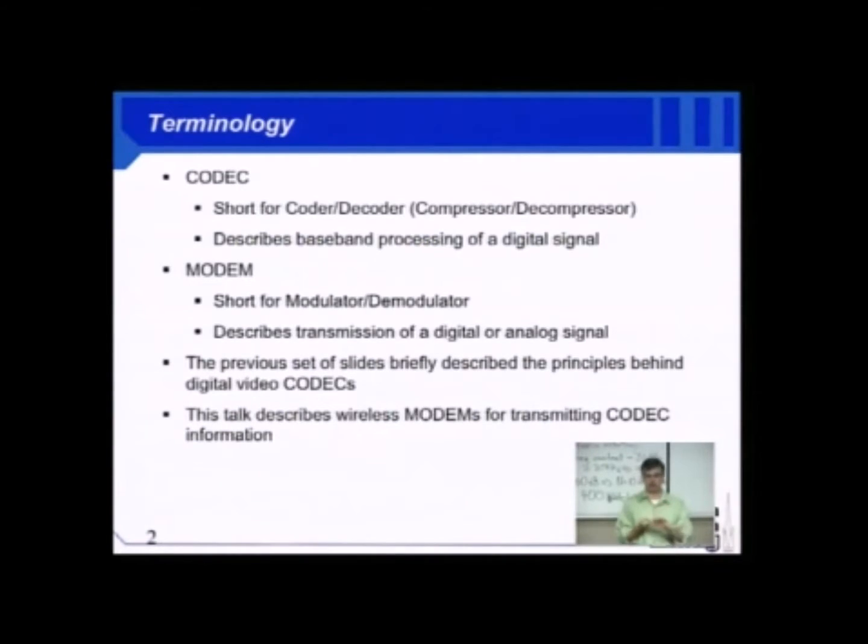What is the pulse shape? So the strategy for representing digital data is I have a pulse that I'm transmitting, a repetition of pulses, and I'm going to use discrete levels and phases of those pulses on the carrier to represent my data. The pulse shape that I pick and the symbol rate together are going to determine how well my signal fits within a certain bandwidth.